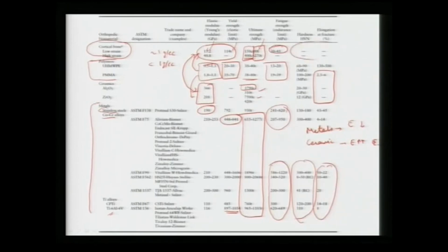And for the cortical bone, there are certain numbers which are not available right now. But again, in terms of density, we can see ceramics have a density on the order of 2 to 3 times that of bone, whereas metals are pretty heavy. They go from 4.5 to around 7.8 grams per cc. So they are approximately 4 to 10 times denser than cortical bone. So again, we need to introduce certain porosity into it, or provide a structure which is much more compliant, and apply a certain coating around it, so it can really interface with the cells or the surrounding tissues.